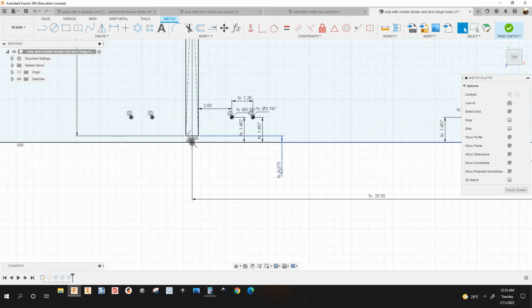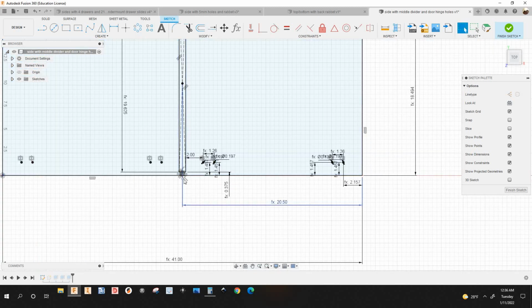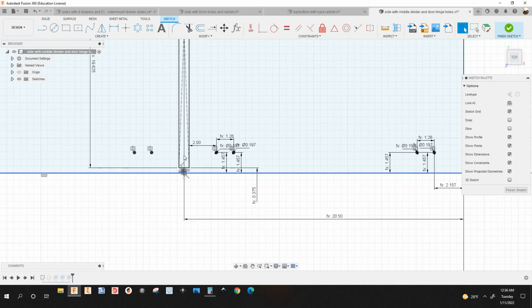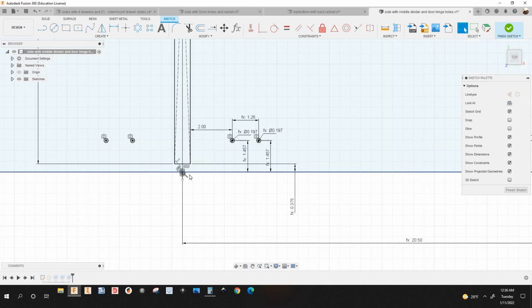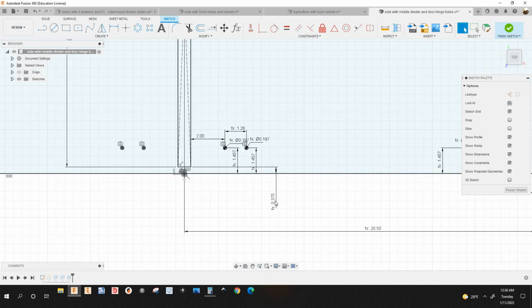And I have a parameter for this divider stop. See that? 3/8. Okay. Let's say I don't want to machine all the way through because the front edge of that side panel is edge banded, and the tool comes out, it's gonna rip out that edge banding, right? So I'm gonna stop right there, 3/8.